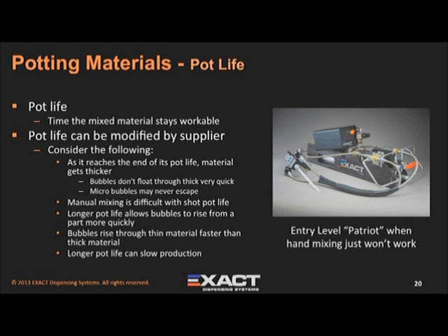It is therefore very difficult to use hand mixing processes when the pot life is fast. When the material gets thick, it is harder to get the air out before it cures. This is one of the reasons we have developed the new Patriot entry-level meter mix machine for users who just can't get along anymore with hand mixing types of solutions.